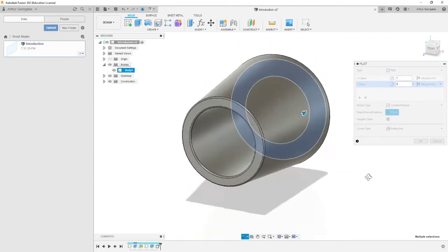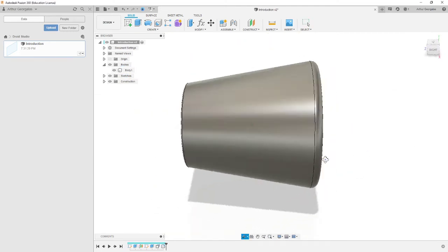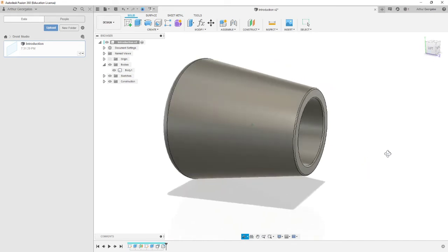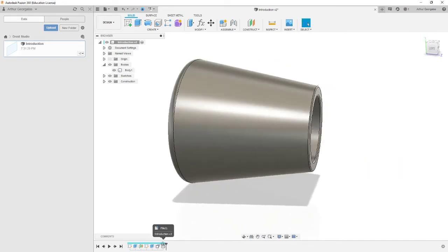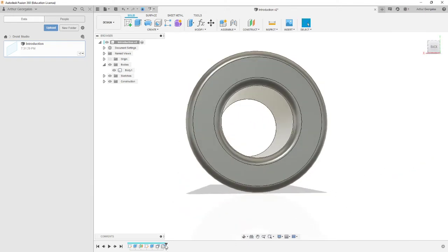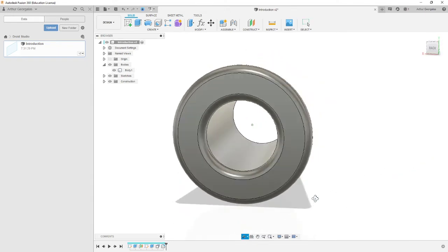And what that does is it allows us to have 2 different kinds of fillets in the one feature, which is super useful because otherwise, a lot of the time, you end up with good modeling, good modeling, good modeling, fillet, fillet, fillet, and it starts to get a bit complicated and annoying. So we want to do all we can to clean up our feature tree.